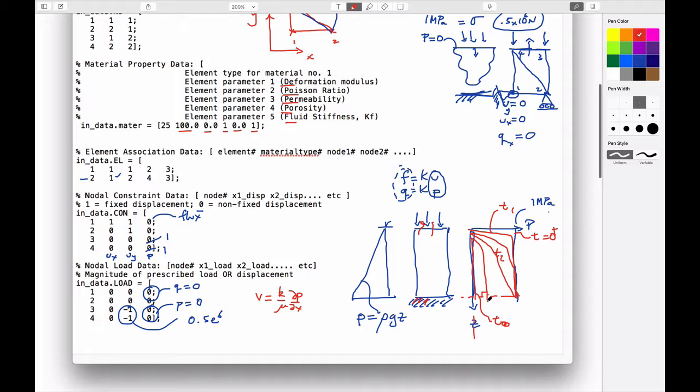In finite differences, often you could think of this being symmetrically a mirror image of this below as it is above. If that's the case, then this has to be perpendicular to the boundary. And if that's the case, then the hydraulic gradient across here by definition is 0. If the hydraulic gradient is 0, because you have this mirror condition, this mirror node on the other side, then there is no flow that goes across here. And therefore, as a function of this being perpendicular to the boundary, there is no velocity, and you've satisfied your no-flow condition. And so we'd expect that to be the case.